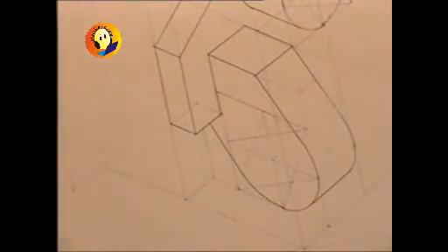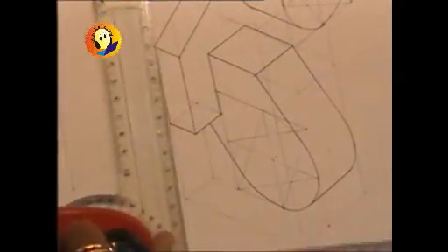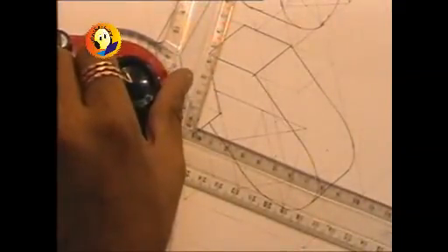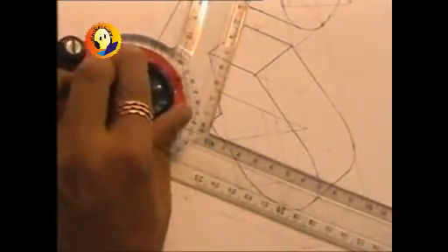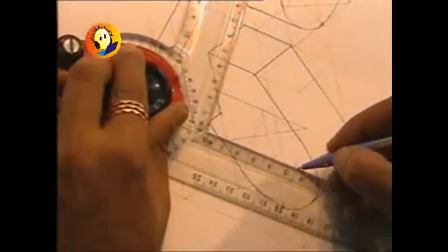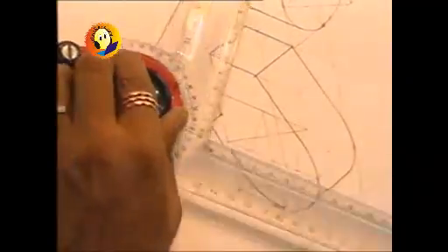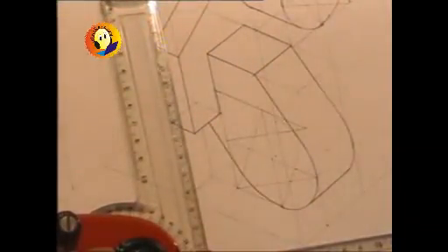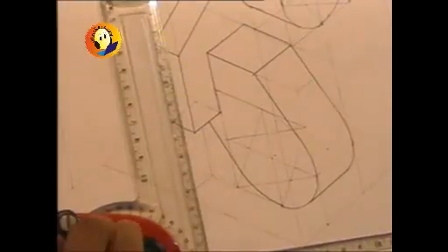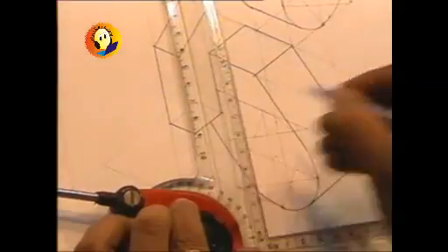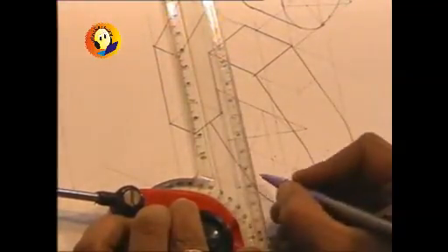Now inside this we are required to have the square whose sides are 30 and the inner square is having a side of 15. So let us first of all construct the outer square. So from the center I am marking 15 mm on each side, and from those 2 points I will be drawing 2 vertical lines, full and final, 15 millimeters on each side, because that side of the square is seen.